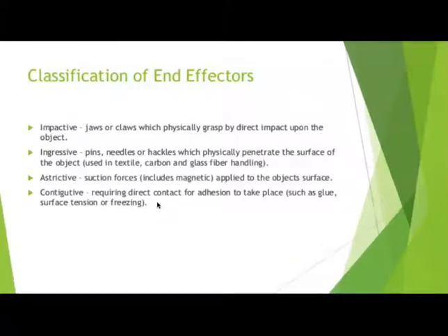As we see here, in the classification of end effectors, there are impactive jaws or claws, which physically grasp by direct impact upon the object. Ingressive means pins, needles, or hackles which physically penetrate the surface of the object, used in textile, carbon, and glass fiber handling.